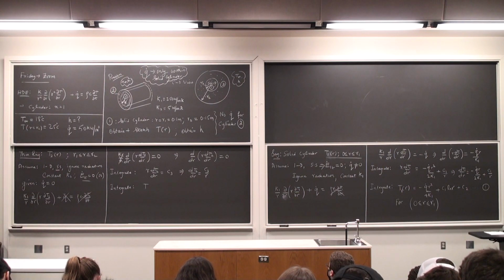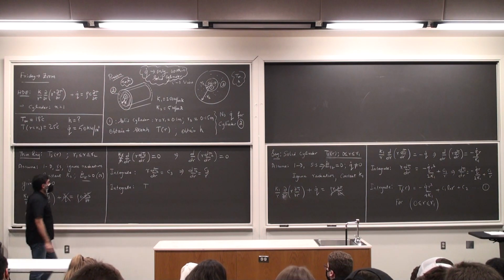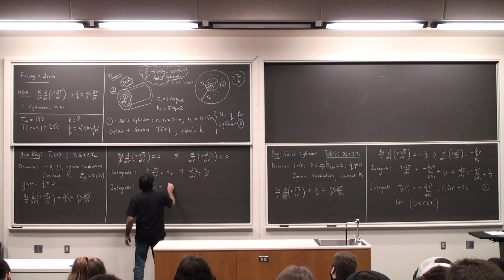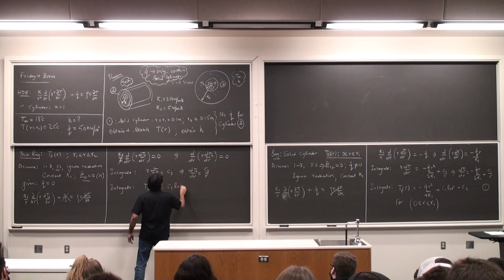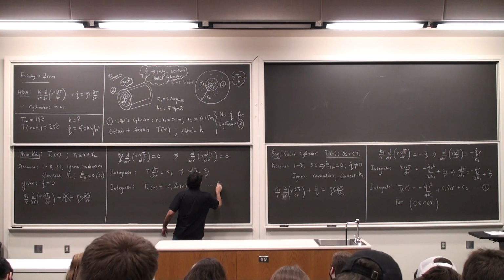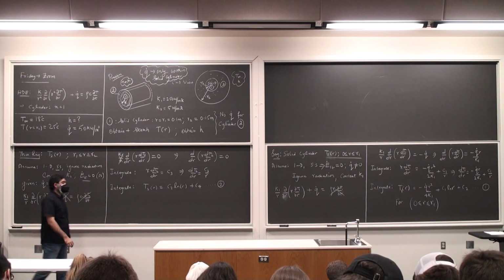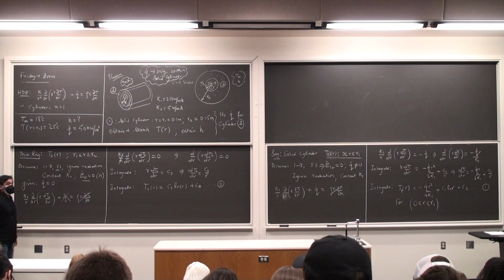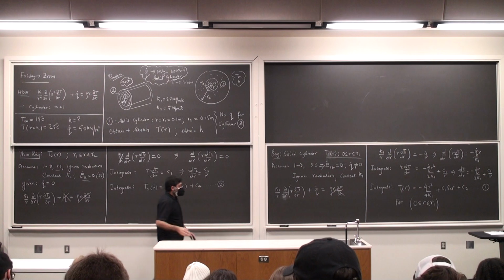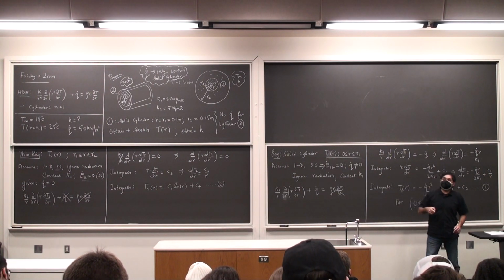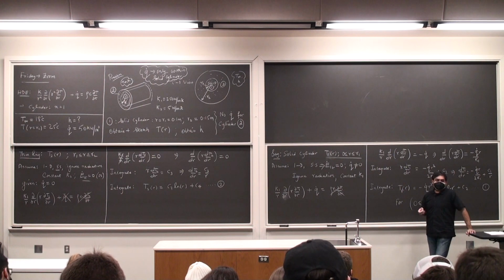So T2 is C3 logarithm of r plus C4. This is equation 2. Once again, logarithm of r does not have any units associated with it, so C3 is going to be in degrees Celsius or Kelvin. C4 is also going to be in degrees Celsius or Kelvin. That's our expectation.